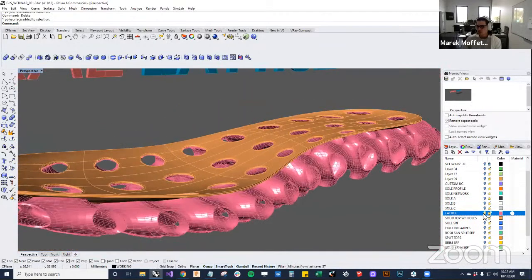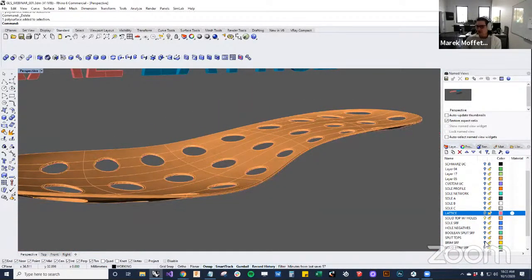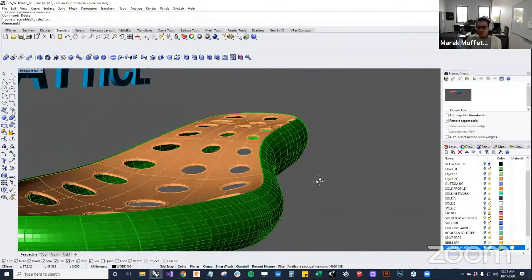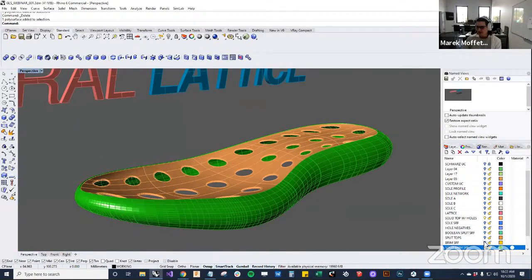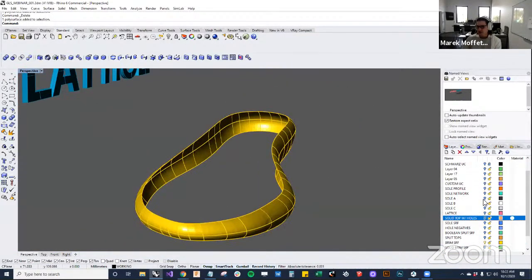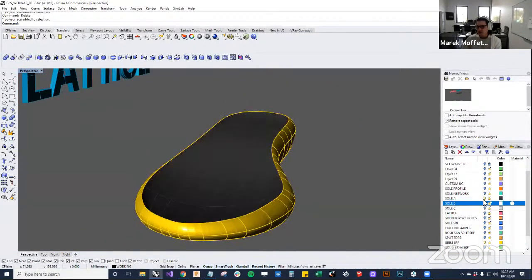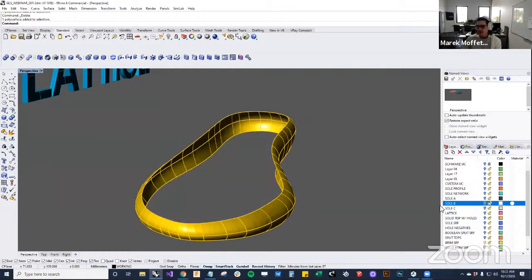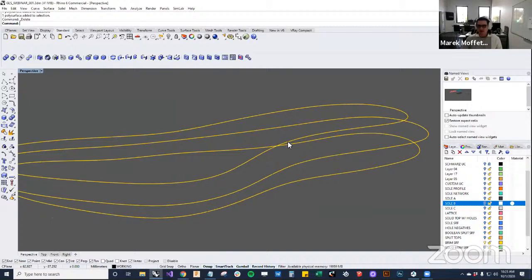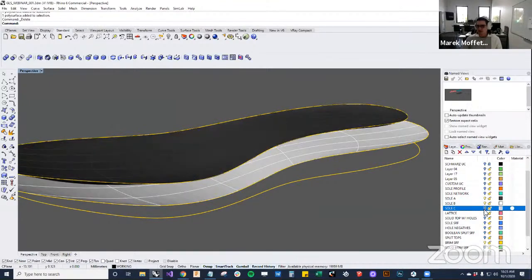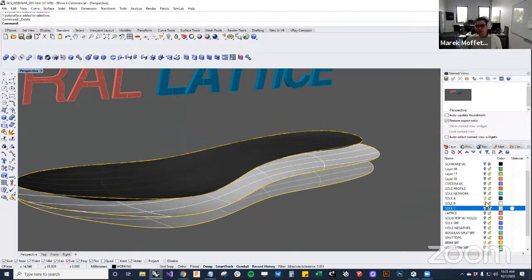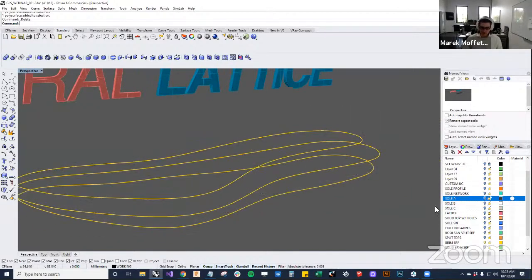And I'll show now how I want to put a brim on this concept. And so what I've done is extracted the edges of these three surfaces, the black, the white, and the gray. And so I'll just recreate this. And these are the edges of each of these surfaces. And so you can see that it's their border. And so what we'll do is a loft command.